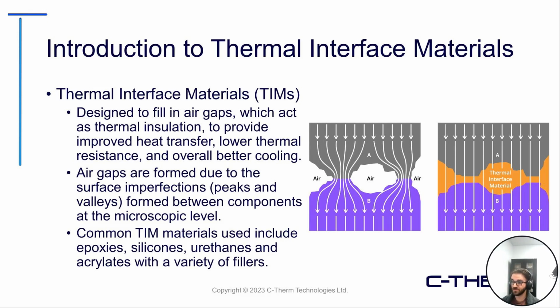Some common TIM materials used, and some that we'll talk about here today, include epoxies, silicones, urethanes, acrylates, different chemistries involved here, but some common examples. And the other note, and this is something we'll get into as well, is a variety of fillers. A lot of the time as these materials are being modified, the base matrix is being filled with certain materials, in this application space typically highly thermally conductive materials, to help further increase performance and heat dissipation of those TIM samples.